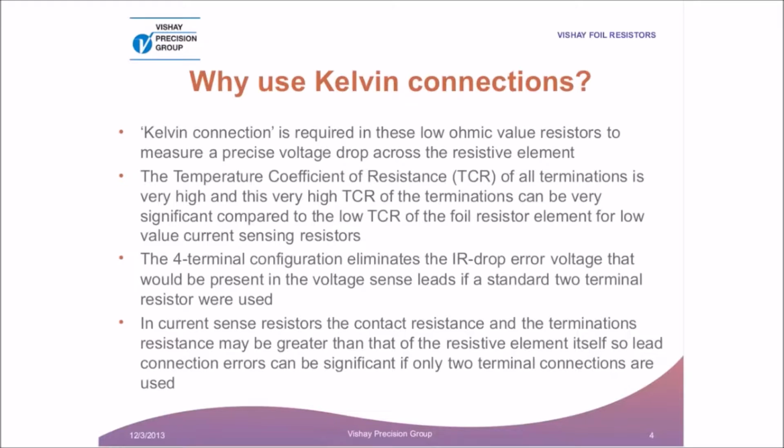With the known and stable value of the resistance R, the volt drop sensed on the resistor indicates the intensity of the current flowing through it. Yes, everything Kevin said, and the Kelvin connection also minimizes or negates the effects of thermal EMFs caused by the long leads, but we'll talk more about that later on.